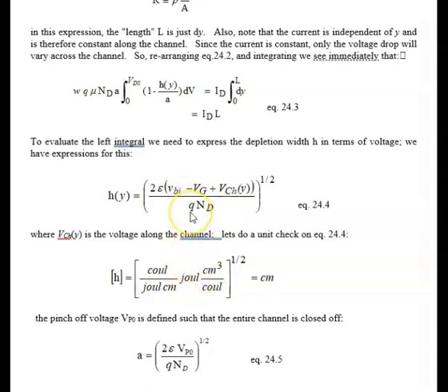And then 1 over QND. The units of ND are numbers per cubic centimeter. That's why we have cubic centimeters on top. And then we have coulombs on the bottom, and the coulombs cancel out. Joules cancel out. Centimeter cubed divided by centimeter squared. And voila, we're okay. So this equation is not only reasonable, it's correct, and you can check it from chapter 20.